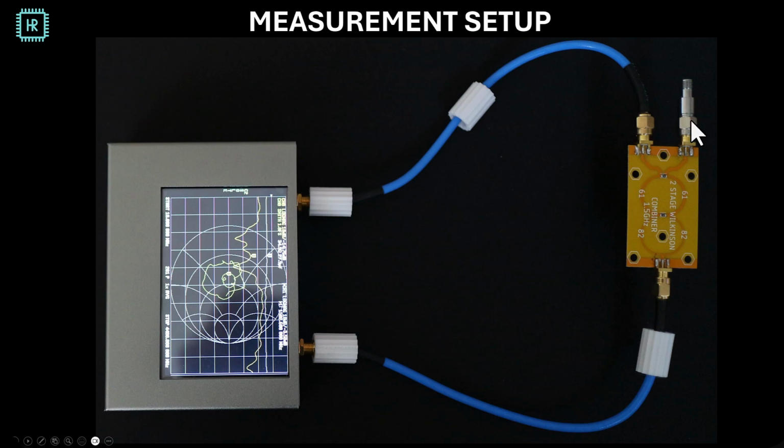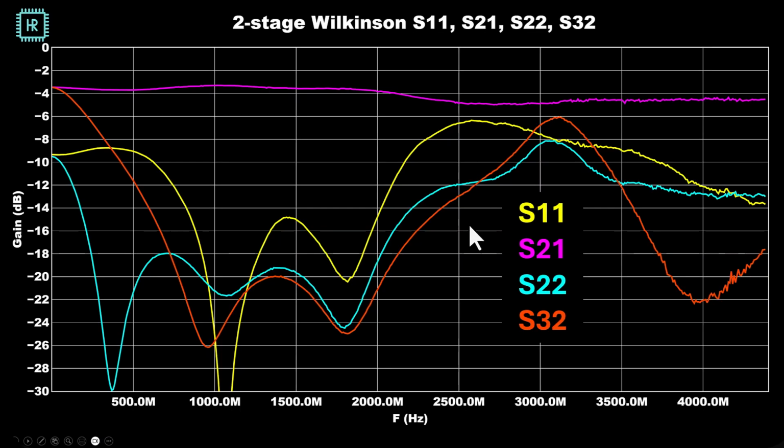But a 20 dB attenuator actually gives you a 40 dB return loss because the signal has to go through there 2 times. It has to go here, 20 dB loss, then reflect back, and another 20 dB loss, so you're at minus 40. So that worked much better because these are 8 gigahertz attenuators. Let's look at the result. This looks very good.